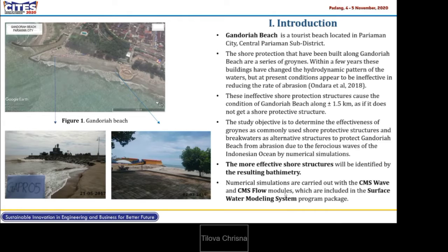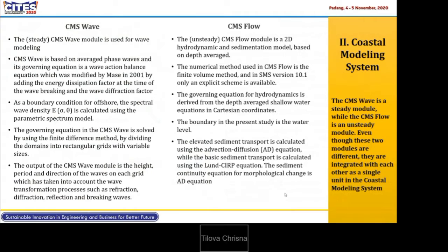The objective of the study is to determine the effectiveness of groynes and breakwaters by numerical simulation. The more effective shore structures will be identified by the resulting bathymetry. Coastal modeling system. The CMS wave is a steady module, while the CMS flow is an unsteady module. These two modules are different, but they are integrated with each other as a single unit in the coastal modeling system.